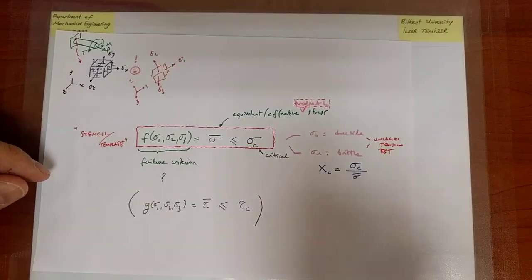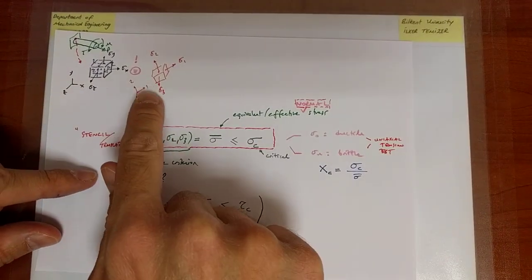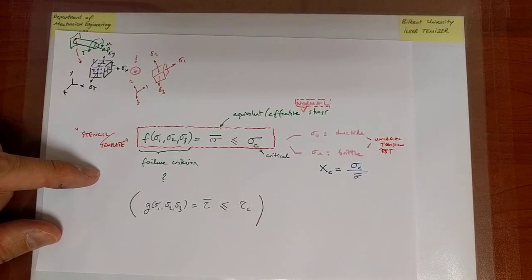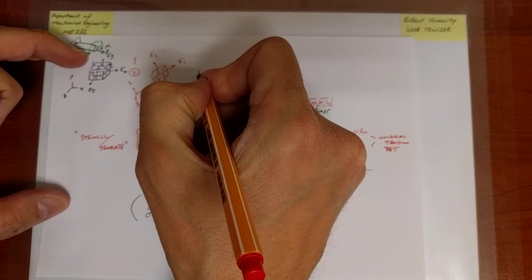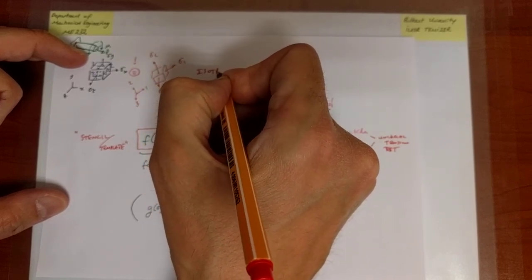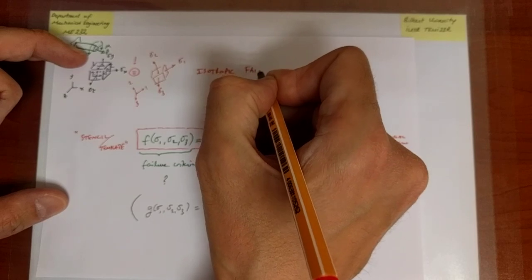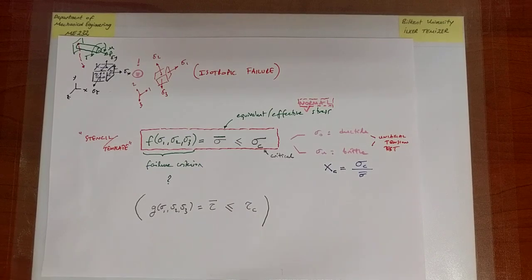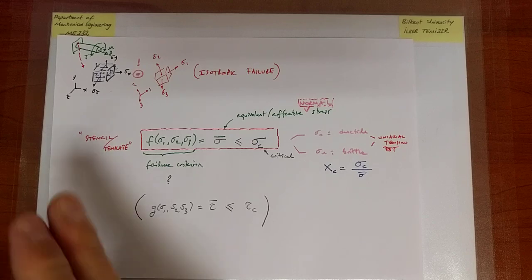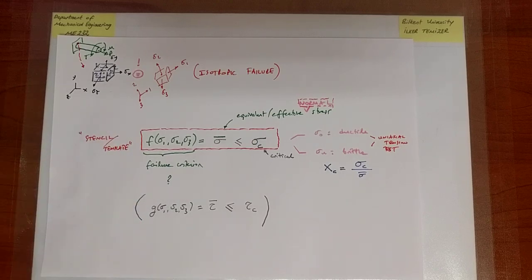So what we have essentially said in our discussion implicitly is that the directions of the principal stresses do not matter, and hence only the values matter, which amounts to saying that we are assuming isotropic failure in addition to isotropic elasticity. Okay. Certainly we could attempt to formulate failure criteria for anisotropic materials, but we are limiting our discussions to isotropic materials just to give you an idea of at least how failure works for multi-axial loading scenarios for materials.